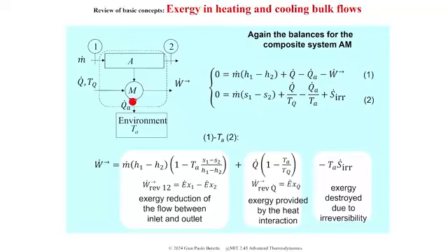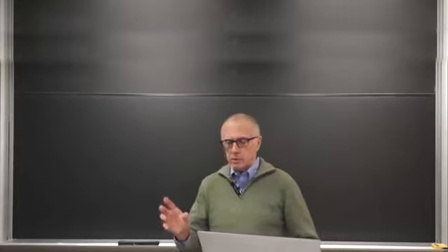for example, you could have a situation in which your machinery not only processes a flow of material, but maybe it also uses heat from some source at a given temperature, and then uses work or produces work. So this would require that you make an energy balance like this. So you have two heat interactions, one with the heat source at temperature T, Q, and the other with the heat source, the environment, which is always there to balance the entropy.